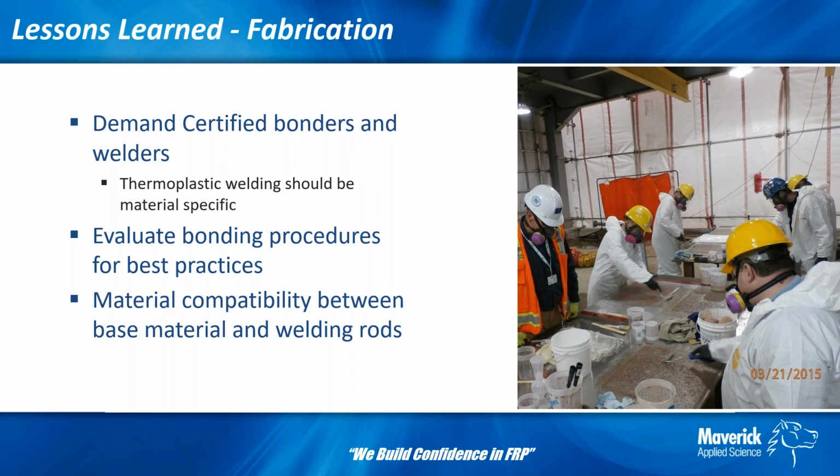So say if it's CPVC specifically, that the welding rods come from the manufacturer or have been proven to be compatible with that specific manufacturer's sheet material or lining or fitting materials. To have one manufacturer's linings and another manufacturer's welding rods doesn't typically work out well. So you want to make sure that they're basically using compatible materials for welding that match the parent materials that they're welding to.